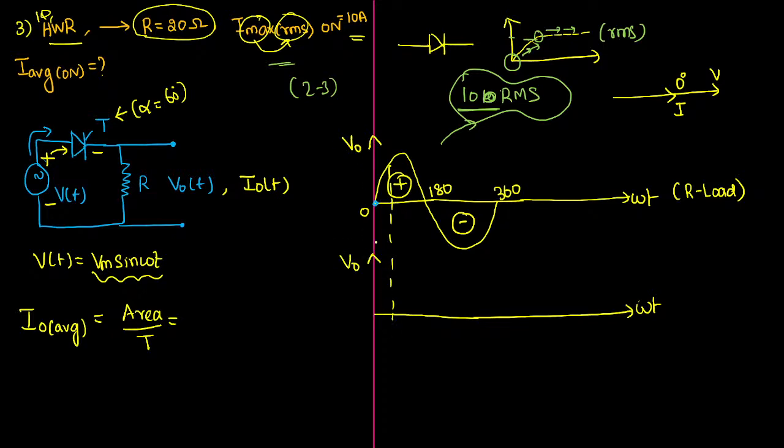I hope you all remember, I told you the supply voltage will be equal to the voltage blocked by the thyristor plus the output voltage. According to Kirchhoff's voltage law, the algebraic sum of source voltages will be equal to the algebraic sum of load voltages. Here the thyristor is a kind of load, the resistor is a load, and the supply voltage is Vs. So the supply voltage must be equal to the voltage drop across the thyristor plus the output voltage.